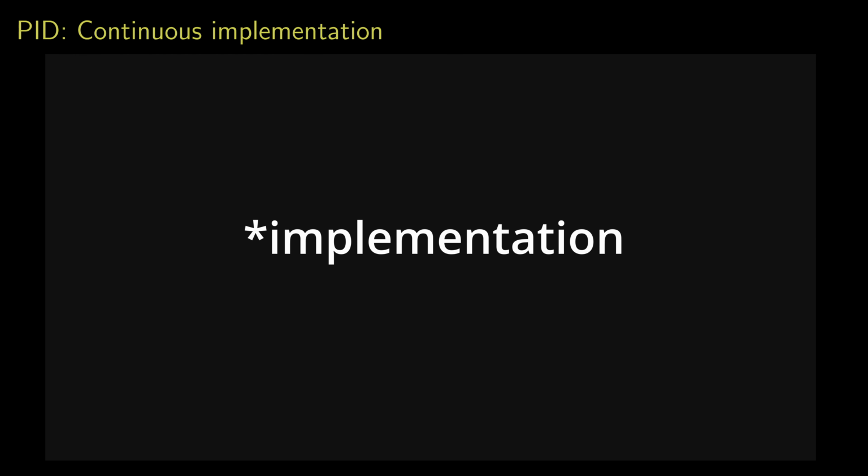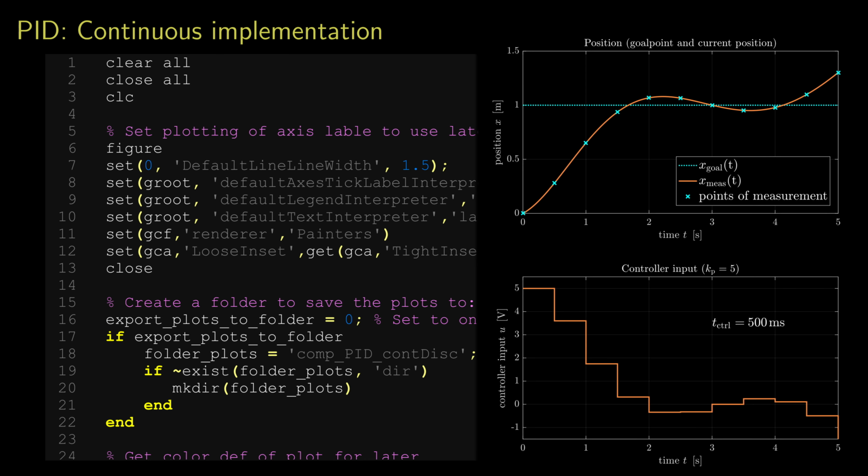What is meant with continuous simulation is that the controller cycle time, so the time span between two measurements where the calculated controller signal is kept constant, is infinitely small, so the controller can act infinitely fast and is not bound to a fixed time interval.